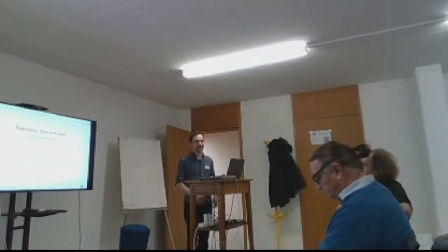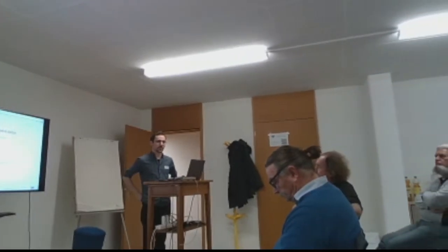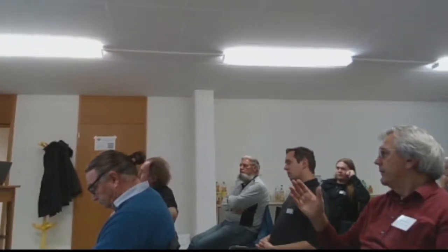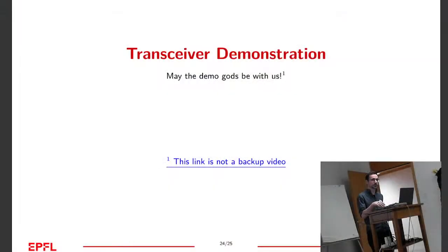And what's the bandwidth of one chirp? It's between 125 kilohertz and 500 kilohertz. So it's relatively narrow. Are there multiple channels available, or do you just get one? For LoRa there are 3 main ones, I think up to 8 that are defined. I'm not sure, but there are at least 5 channels that you can use one beside another. And how are the channels chosen? How do the devices choose which channel to use?